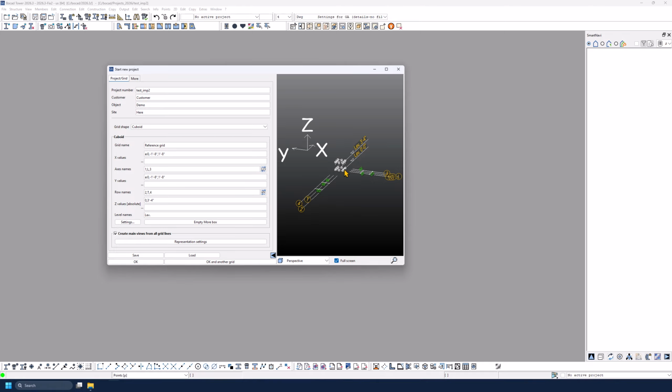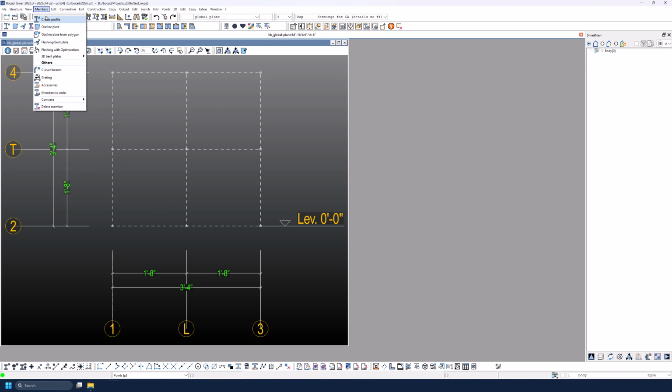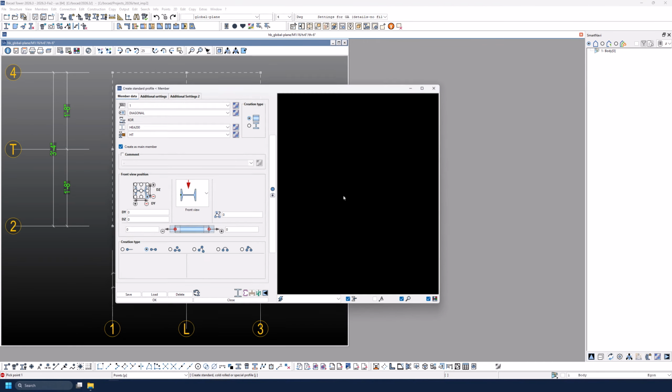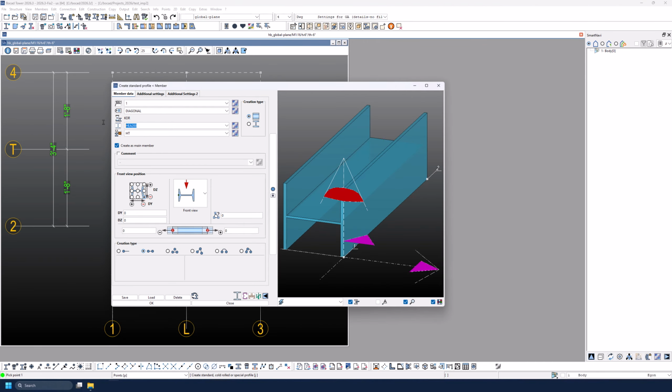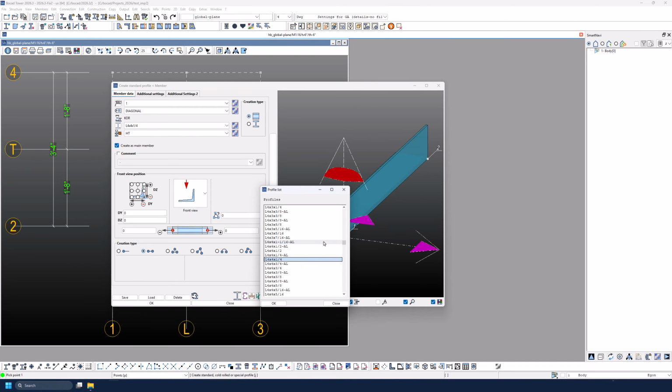My grid is also represented in a better way. Here also I have my round values. And then I can go to profile. See, for example, now an L150 by 10 is not allowed. But if I say I need an angle of 4 by 4 by a quarter, for example, that one should be available, since now we're picking from the imperial database, which is here.